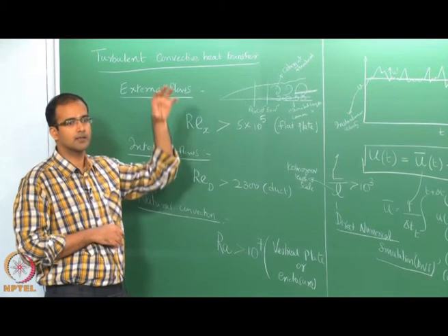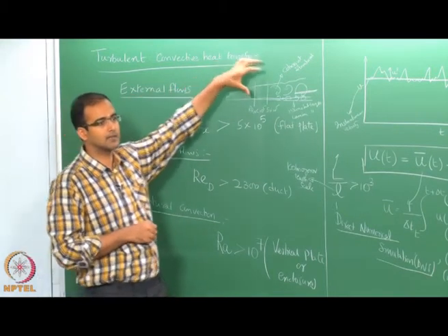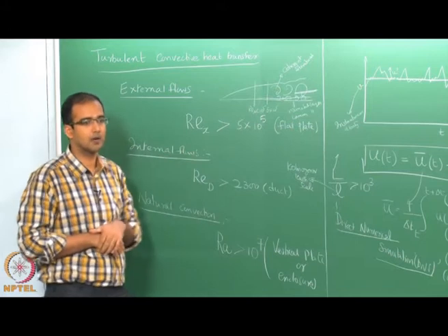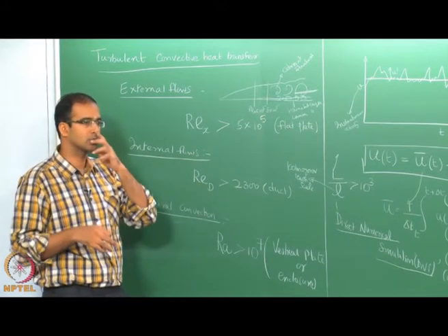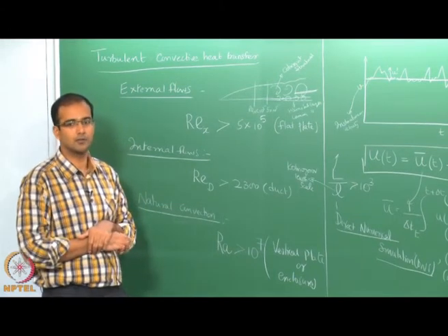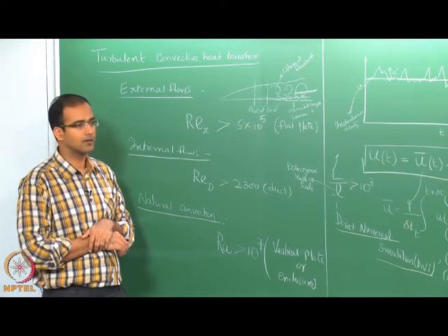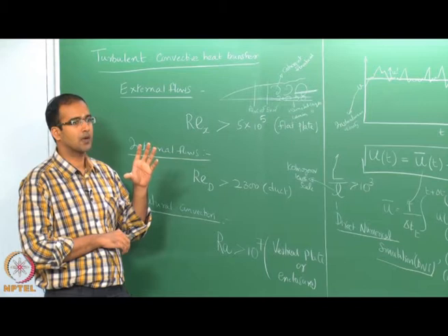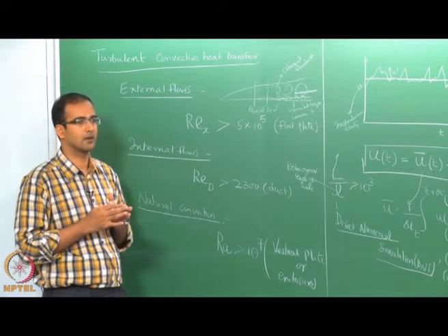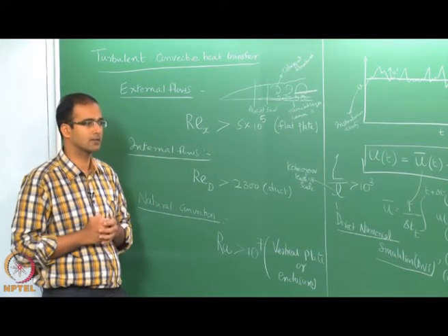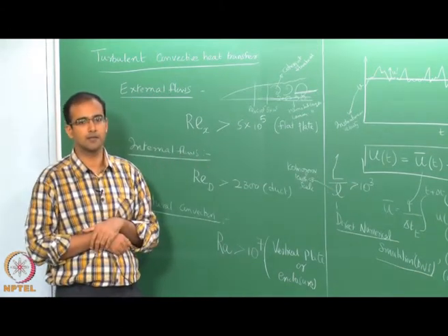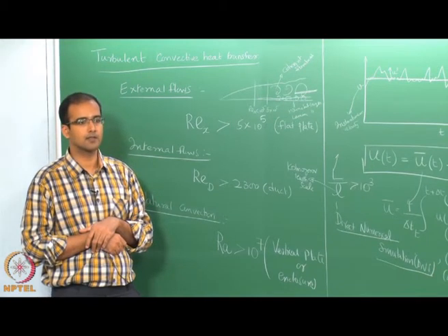Finally, all this turbulent momentum coming from the larger eddies is actually handed over to the smaller and smaller eddies, and finally the smallest eddy will dissipate this. There is nothing else to take away this energy from the eddy. So, but it dissipates itself into heat due to viscous dissipation effects at the wall. Okay. So, generally when you do a DNS, you plot the energy spectrum and show that you have resolved all the energy scales of turbulence right from the largest scale to the smallest scale, and these length scales can be at least 10 power 3, the ratio of the largest to the smallest length scale.